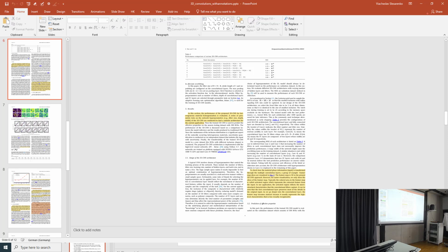With polygons, for this particular problem, polygons are bad because you have sharp corners, and therefore mechanically you have problems there. You will have some concentrations of stresses, and that's something that you do not see in circles. You still see a distribution, but it is not infinite. So that may not be a great idea. To be honest, the fact that they did it in 3D is quite amazing, because I run simulations in 3D, and one simulation takes 2 hours minimum, because you need to mesh everything. So it's insane.